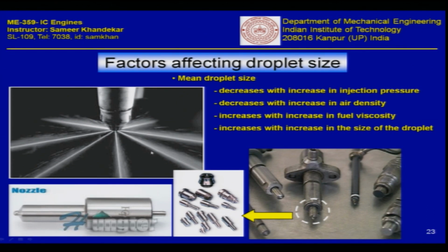So, the density difference between the liquid diesel and the air has reduced, because the air is thin at 1 atmosphere, but it becomes pretty dense at 30 atmospheric pressure. We can easily calculate what will be the density of air at, let us say, 30 bars or 40 bars, and in that condition, when the density is high, you have to do the injection.